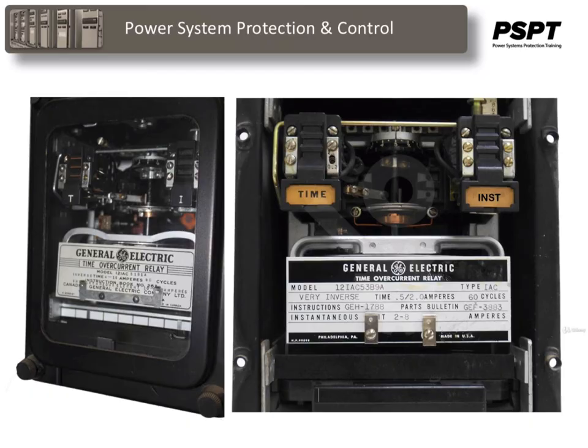The overcurrent relay is the simplest type of protection relay. As its name implies, the relay is designed to operate when more than a predetermined amount of current flows into a particular portion of the power system. There are two basic forms of overcurrent relays: the instantaneous overcurrent relay and the time delay overcurrent relay.